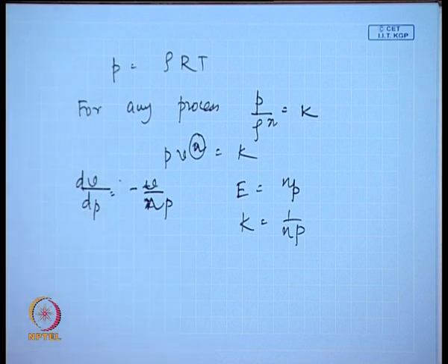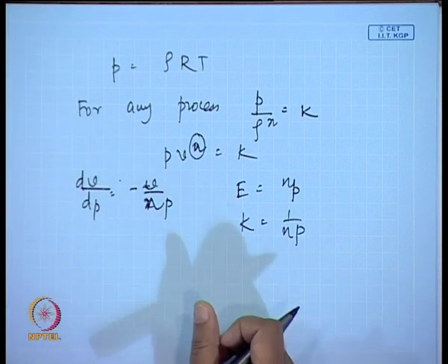Now, whenever a fluid is at rest, its density or its specific volume changes with pressure. We can define it either with bulk modulus of elasticity or with the coefficient of compressibility. Whenever we define it in terms of compressibility, since a change in pressure brings about a change in volume as well as a temperature, it has to be an isothermal coefficient of compressibility.